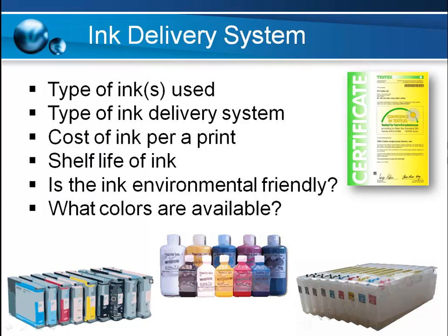The final thing on the inks is what colors are available. Typically, the standard colors are cyan, magenta, yellow, and black, or CMYK, and then white. Hopefully in the near future we'll start to see more expanded color gamuts using light magenta, light cyan, light black, or red, orange, green, and other colors that will expand the actual printable color gamut.